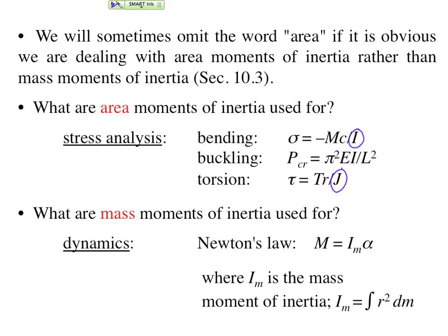Instead of talking about adjacent cross-sections rotating with respect to one another in bending, torsion is a mode of deformation where adjacent cross-sections remain parallel but twist with respect to one another. If we were to score a straight line on an undeformed cylindrical shaft that subsequently transmitted the torque along its axis, that straight line would deform into one with a helical pitch.